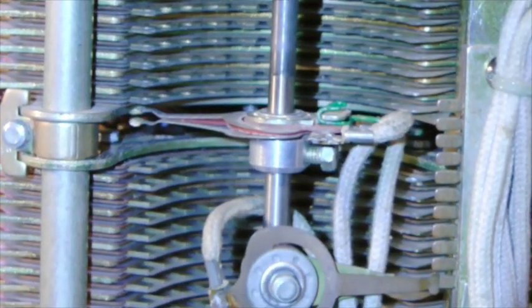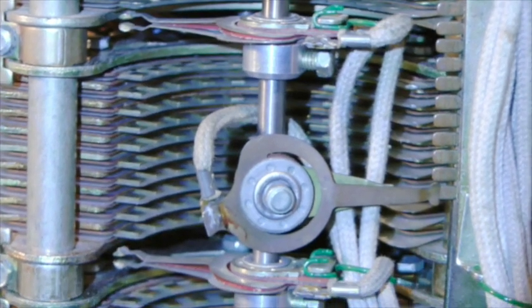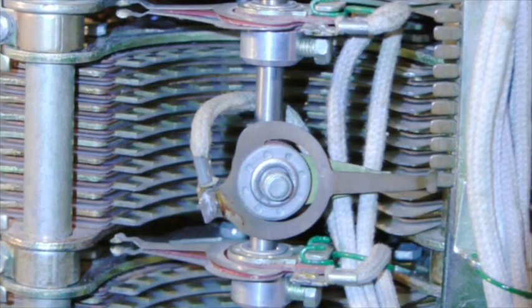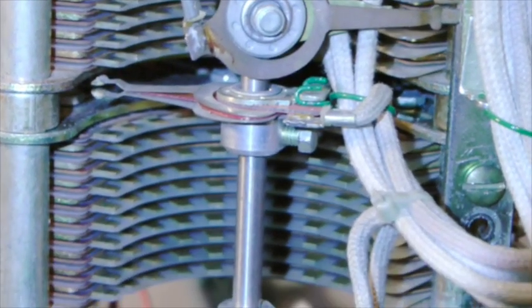In the middle tier, the top side terminals are the ring transmission terminals, and the bottom side terminals are the tip transmission terminals. These 100 tip and ring sets are associated with line circuits numbered 100 to 199. In the lower bank tier, the top side terminals are the ring transmission terminals, and the bottom side terminals are the tip transmission terminals. These 100 tip and ring sets are associated with line circuits numbered 00 to 99.